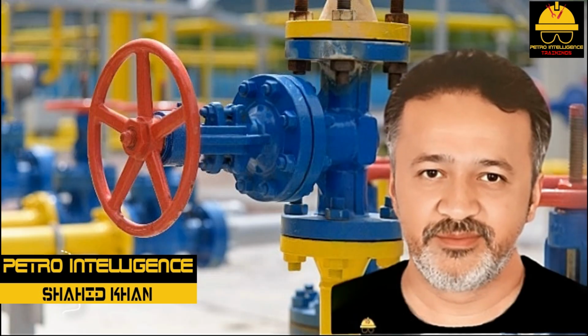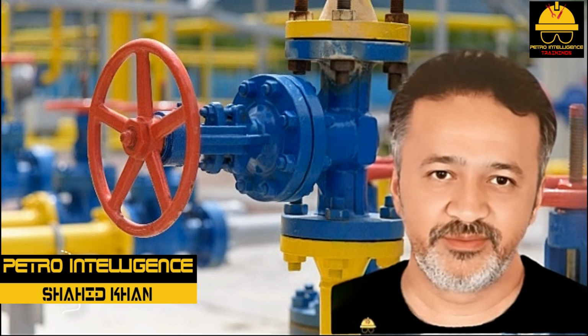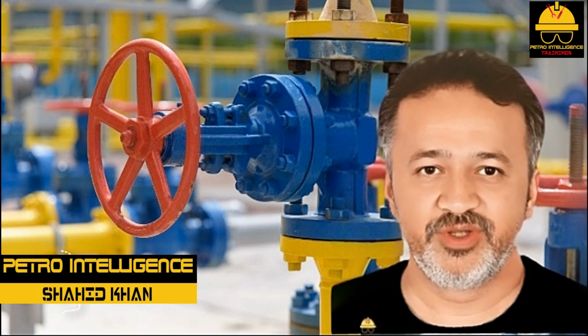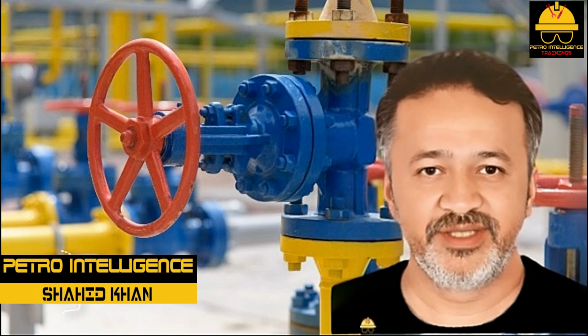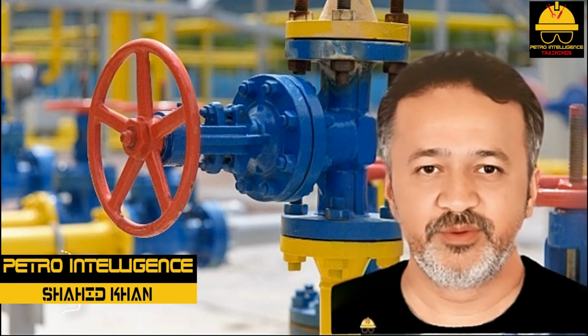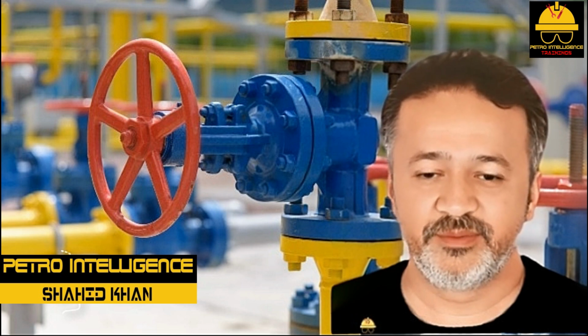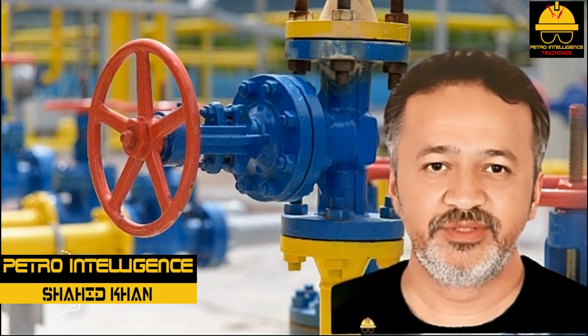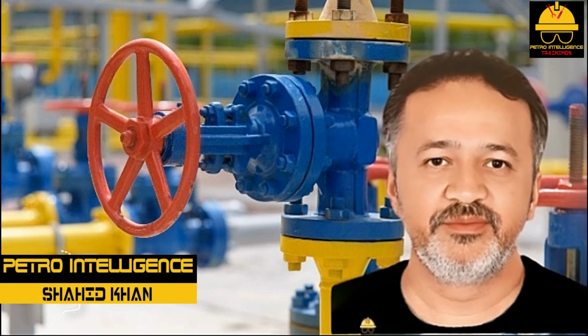Hydraulic actuators. Hydraulically operated actuators are very strong. They convert liquid pressure to mechanical energy. The hydraulic actuator uses a liquid-tight cylinder and piston to move or position the stem. It is commonly found in use with automated gate valves or slide valves. It is used where a lot of stem travel is needed.